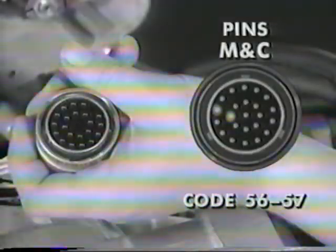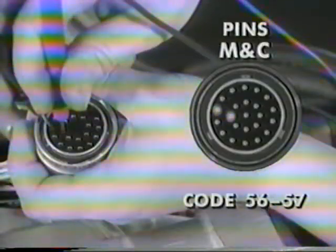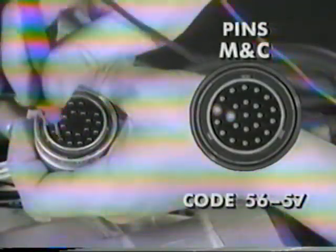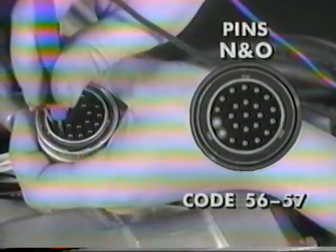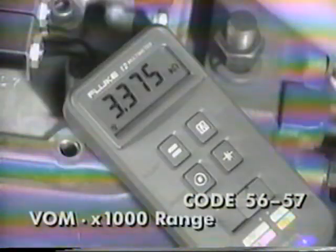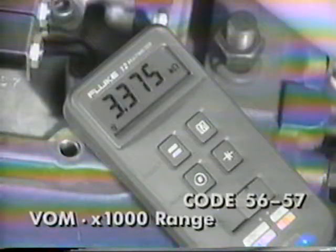So, to perform these tests, again, start by removing the shift bar cover and disconnecting the auto shifter harness from the ECU. On the auto shifter harness connector, probe pins M and C for code 56 or pins N and O for code 57. The resistance should be 3 to 4 k ohms.